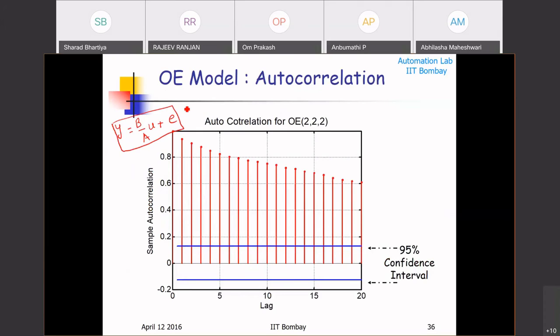So you can find out the coefficients of these polynomials. So what is time series modeling, or what is system identification? It is finding out b1 to bnb, there is no b naught, I discussed that with you, and finding out a1 to ana. Finding out these coefficients means your model is done, because now you can plug these back over here and use this model for prediction.